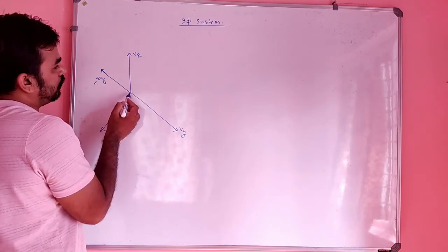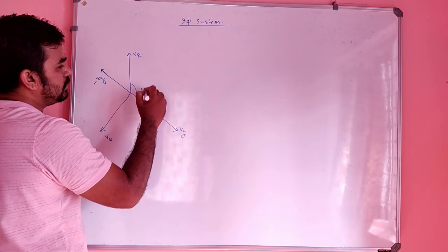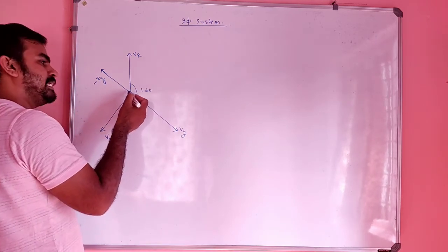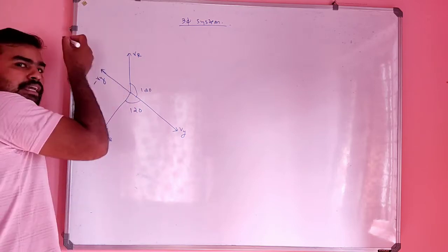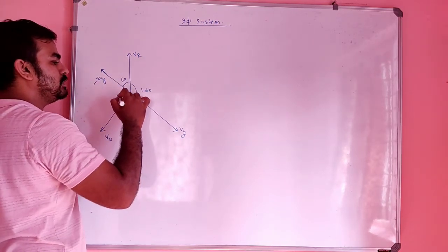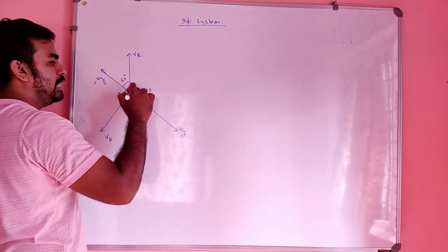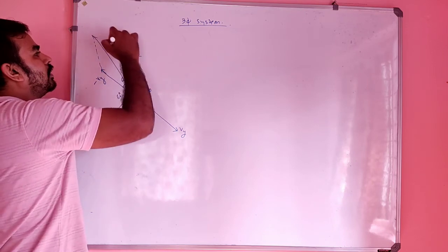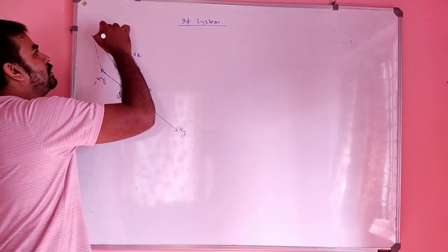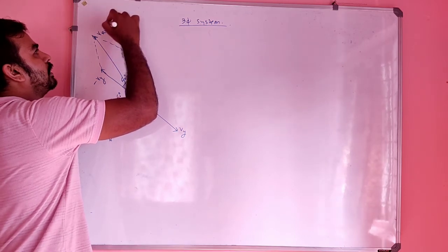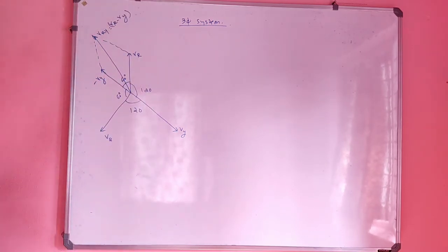See, when you cross, all are 120 degree, right? This is 120 degree and this is also 120 degree. When you project exactly in the middle of this vector VY, this will be 60 degree, and this will also be 60 degree. And the resultant will be like this. This is nothing but VRY, which is VR minus VY, correct?